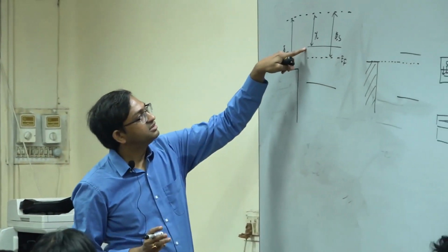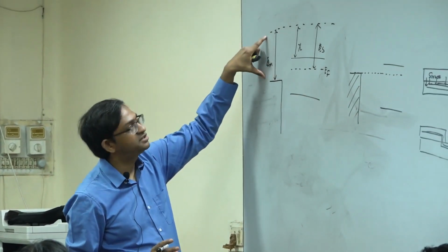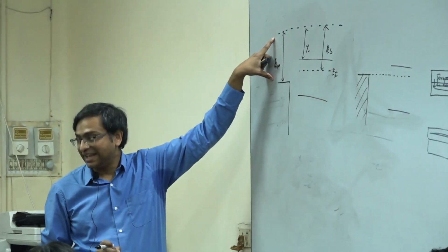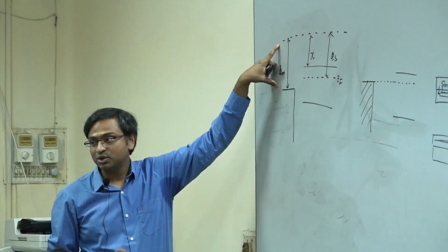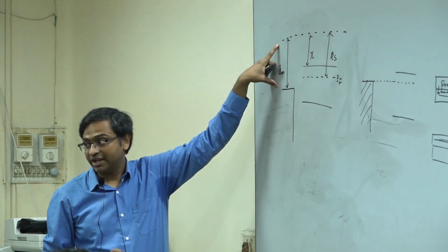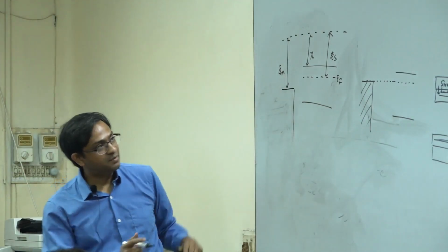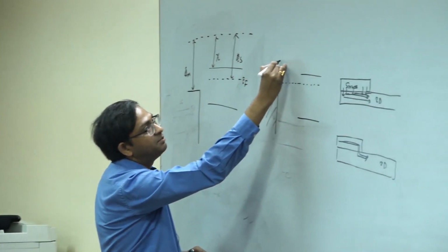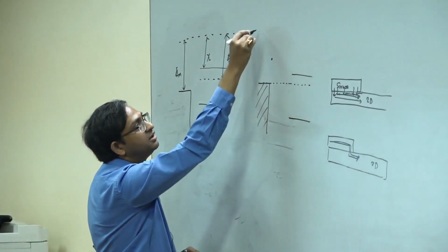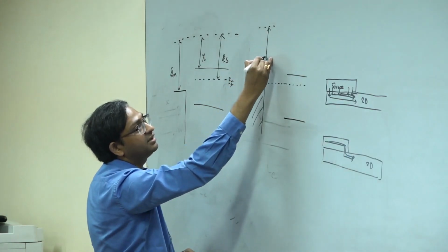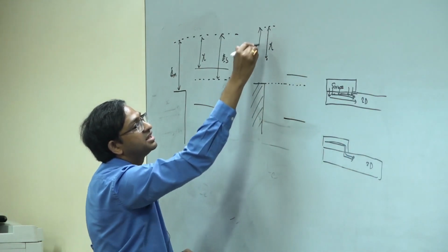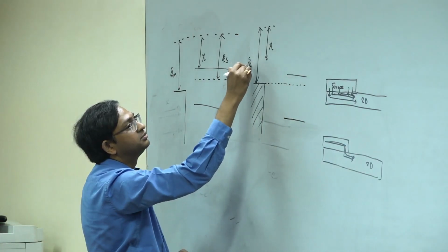That's rule number 2. Rule number 2 is the difference from the vacuum level of these two has to be maintained at the junction. Right? How can I do that? How can I do that? I can only do that if the band is somewhere over here, and let's say this is a vacuum level, so that this distance is chi, this distance is phi m.